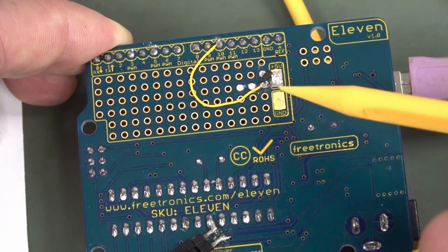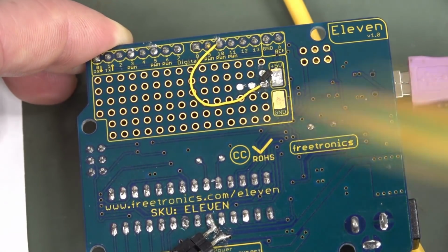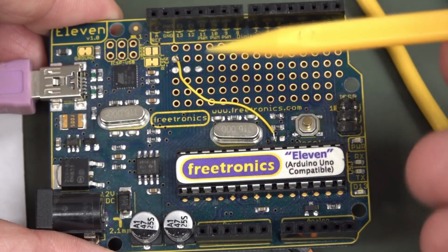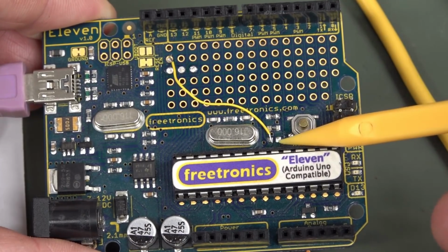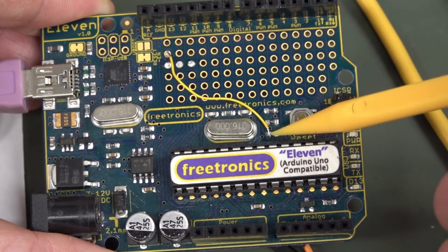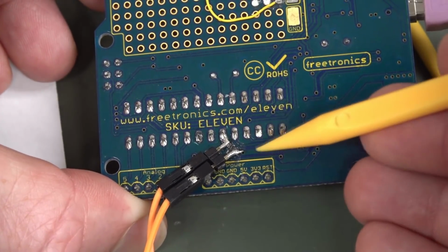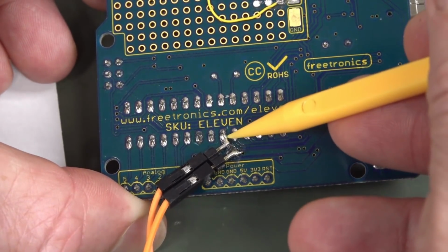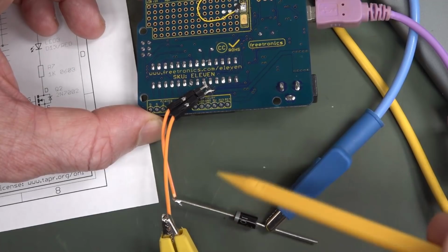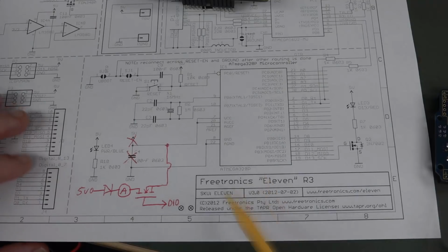So then the software can switch on and off its own power and do that at the PWM rate, which I think is like 400 and something hertz for the Arduino Uno. And then on the top side here, I've removed the bypass capacitor. I'll show you the schematic in a minute. Basically, I'm feeding the output of the MOSFET to the power pin, both analog and digital power. I've cut the trace down here, so this is the 5 volts going in to the analog VCC and the digital VCC up here. So we can whack a current meter in series with that and measure the consumption of the processor as we switch the power. So you can see what I've done here.